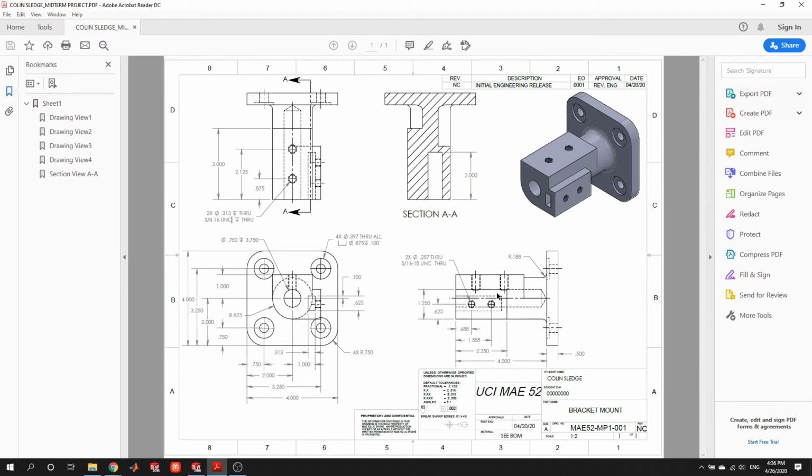Now, if we want to represent how this hole goes into the feature, we'll need to keep that conical tip, because if we were not careful, for example, and this hole went too deep, that might actually go through the base of the part. And so that would represent in real life, if we were to drill the same hole, that might go through the base of the part. So there's a lot of reasons why it might be nice to represent that real conical tip on the part. And then of course these threaded callouts.